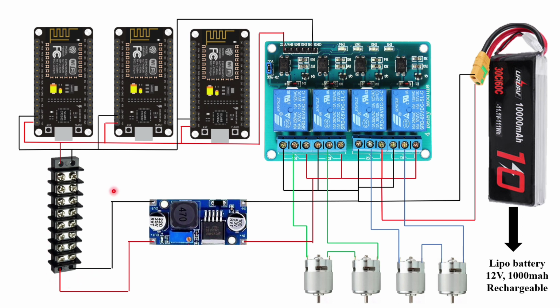And then I'll just finish off my starting part, that is, at the front side what all components are there. Actually there is only the battery, a charger and one 4 channel relay module you can see, and on the side a buck converter. I have used 3 relay modules here: one of 8 channel, one of 4 channel and one of 4 channel. All these relay modules are used as switching devices. I have used them as switching for motors, as well as for lights, for fan control, and for my forward and reverse motor direction also. I have used a relay module only.